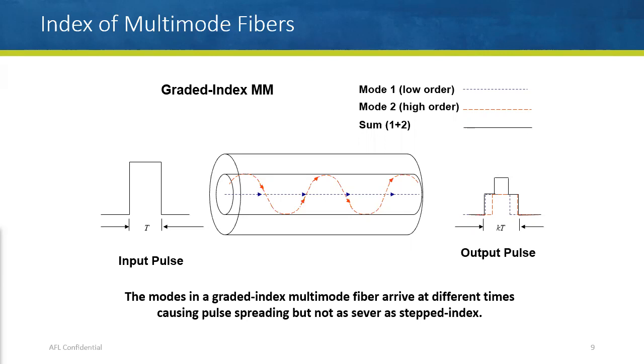So you get less spread on that output pulse, which allows us to go with sometimes longer cable runs, because the further you go down this, the longer or the wider this pulse gets. And so you get to the point where you end up with pulses stacking on top of each other, not being able to tell when one is on and one is off.